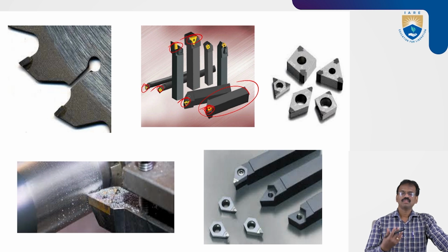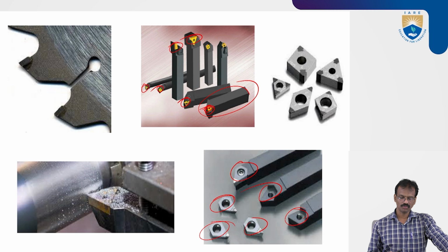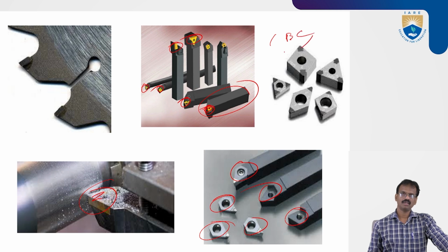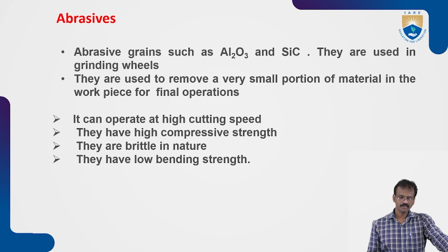Okay. So next we can insert these cutting tips on the cutting tool, low carbon cutting tool or high speed cutting tool, whatever it may be, you can see like this one. So in this place we can set CBN materials or diamond or ceramic materials, whatever, based upon the workpiece material you can choose the tip materials. Okay. So these are the materials.